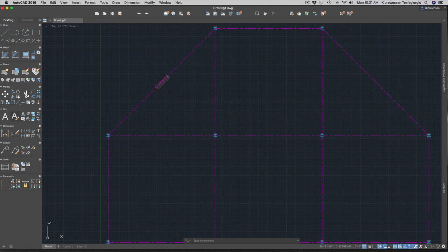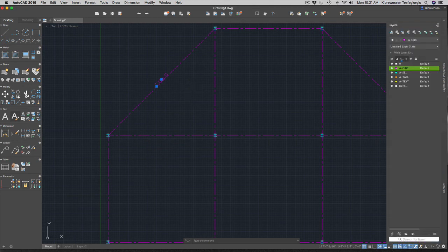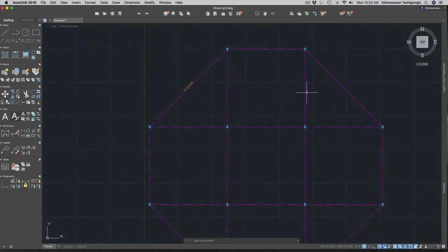Okay, so this is single line text. In single line text, if you press enter once, it moves to a new line. If you press enter a second time, it exits. You can simply move it a little up. Then just change the text style to text, because it's a text. See, that's how you will write them.